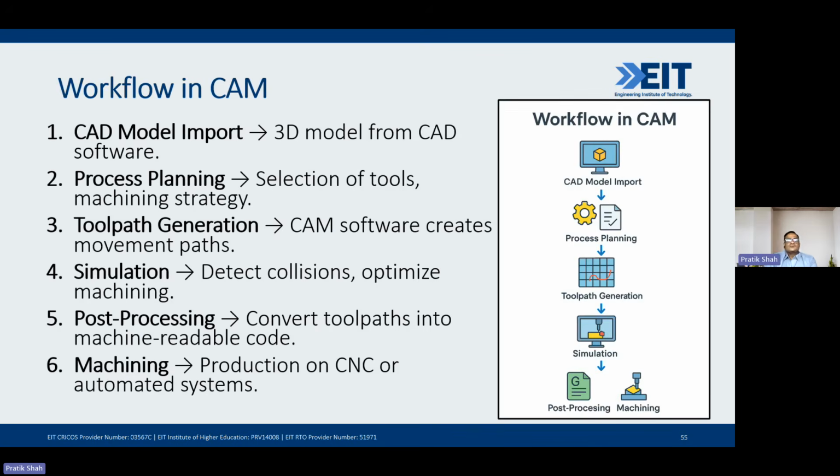And I would now like to stress the workflow of the CAM. The CAM process basically starts with importing the CAD model. As I told you, the output of a CAD model can go to either analysis or manufacturing. So what people do is import the CAD model from the CAD software into a CAM software, which is shown over here. The second stage is process planning.